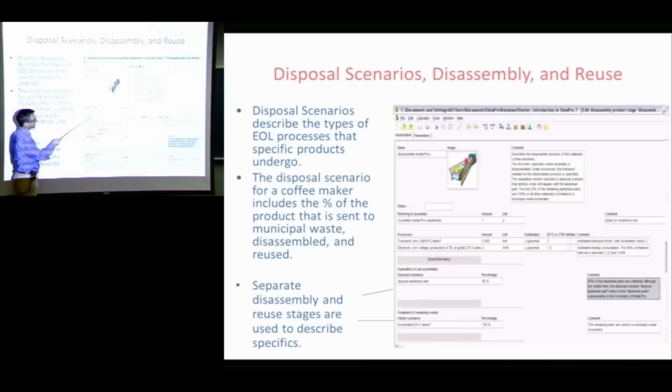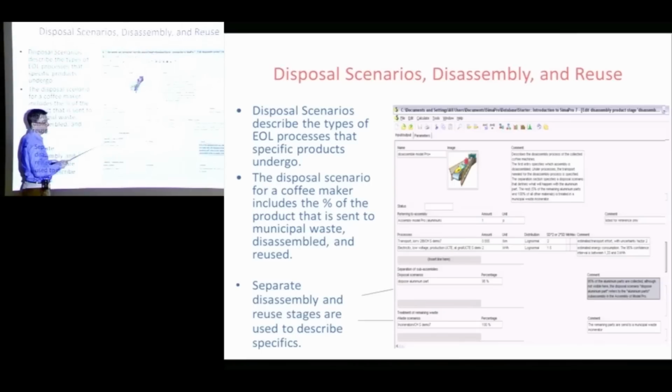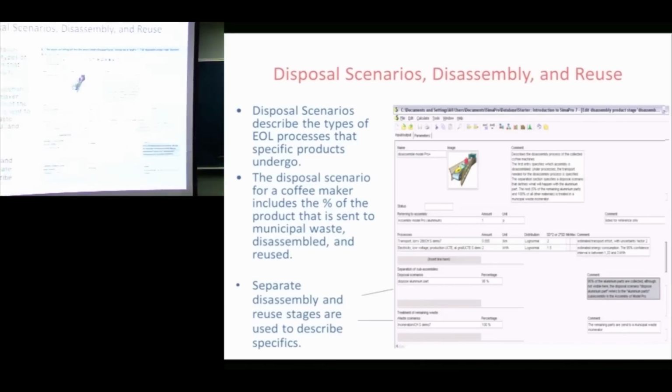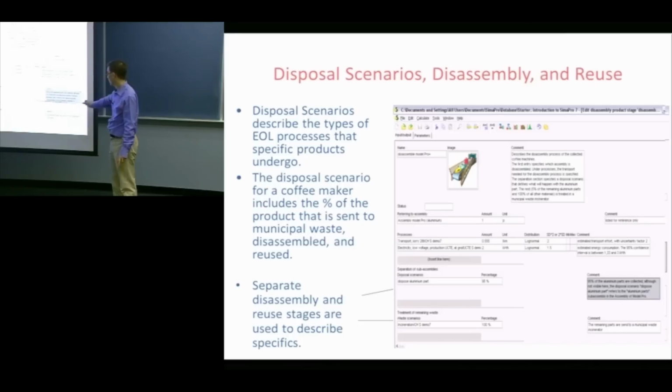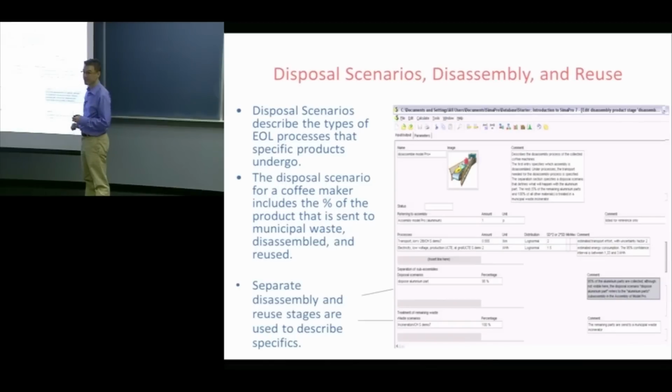But we've got that assembly model, where part of that disassembly is going to be transported somewhere else. There's going to be some electricity used to disassemble the product. And then for the aluminum, in this case, 95% of that aluminum is actually going to be disposed, which might be a little bit surprising. But there's a note over here that says, although the aluminum parts are collected, the disposal scenario refers to the aluminum parts. So in other words, you've got aluminum parts that have already been separated. So this is the extra aluminum, and it turns out to be not a lot. Basically, it's that aluminum that's hard to get. So you can get down to that level of, okay, that subassembly is hard to get. It's aluminum, and we're only going to get about 5% of that. Right, so very nested and somewhat complex.